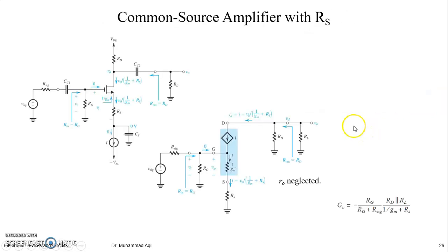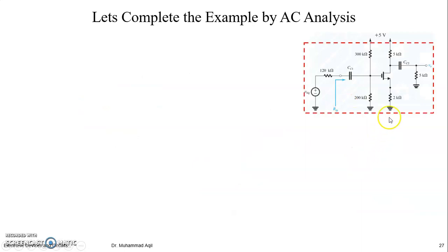So it means we have to use this model. Let's do it. This would be the whole AC equivalent part. Only this will be grounded, this will be shorted, this will be shorted. Then you can replace your transistor with the T model. The T model is gate, drain, source, with a gate-to-source internal resistance, not externally. And then the drain behaves as a current source controlled by this VGS.